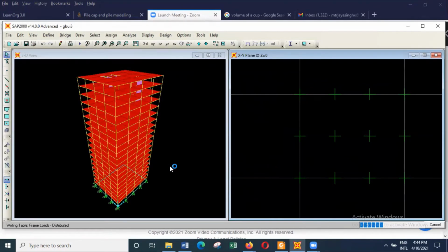So I'll go to the third one. And now you can see the loads are something like 9,000, 8,000, that type of range. So the question is, what type of foundation will we use for this building? Because I'm planning to convert it to a 30-story building later, just for comparative purposes, I will go ahead with 4 piles under each column, though it may not be necessary everywhere. I will use 4 piles of 1 meter diameter under each column, because a 1 meter diameter pile can generally carry about 4,000 kilonewtons of load.